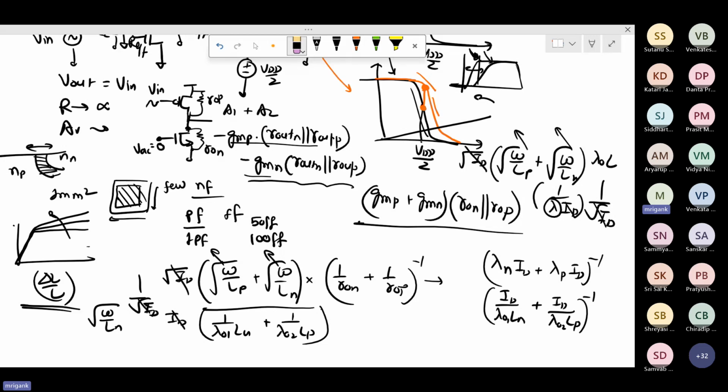In this case, we have a simple inverter, and with the help of that you are getting it to operate as an amplifier. And the gain-bandwidth trade-off, just like we are seeing here, is available. The same thing is happening in other amplifier topologies also. Any question before we conclude?